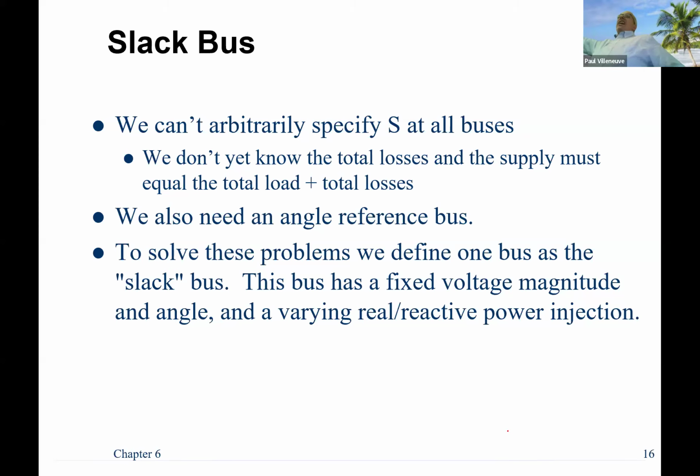So with that being said, I have no way of knowing what the P and the Q injected at the slack bus has to be, right? Because that bus can either absorb or supply any amount of real and reactive power. So I can't write power balance equations for the slack bus, can I? Because I don't know what PG and PD or QG and QD are for those buses. That's a problem, isn't it? Because I need equations to solve to be able to check my answers are correct.